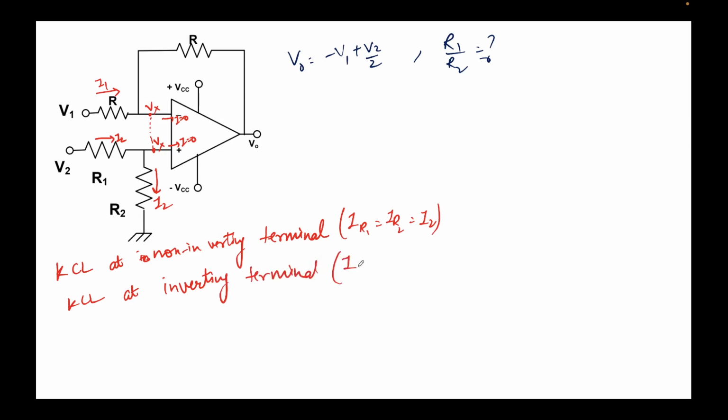again, the current flows through resistor R, this one. Since no current is flowing through this arm, if I apply KCL at this node, all the current that's coming through this direction has to flow here. So the current through R equals the current through RF, which I'm denoting by I1.